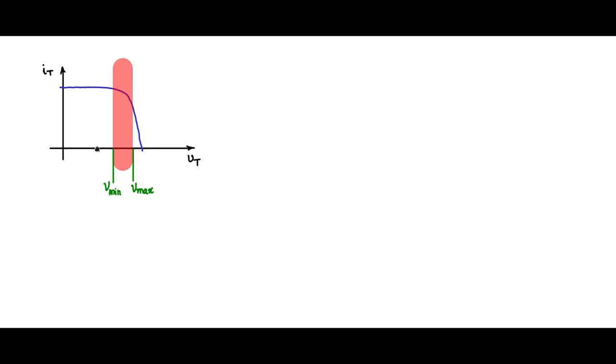then you know that the battery is not in the charged condition, and therefore the battery has to get disconnected from the load. So for battery voltage less than this, the battery has to get disconnected from the load. It will get directly connected to the PV panel, so it will be charging with almost the full PV panel current. And in this region above Vmax, we don't want the battery to charge any further, we don't want the operating point to shift any further to this side, and we will connect the battery to the load and disconnect the battery from the PV panel. So that is the logic.